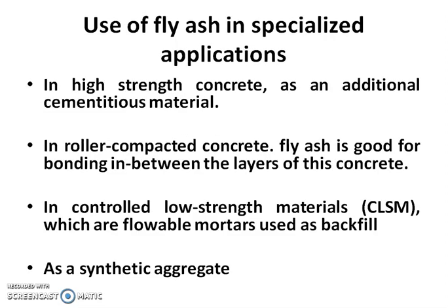What is the use of fly ash in specialized applications? We can use it in high strength concrete. In roller compacted concrete, you can use it. As a synthetic aggregate, we can use that. In controlled low strength materials, we can use it as a flowable mortar, particularly for the backfill.